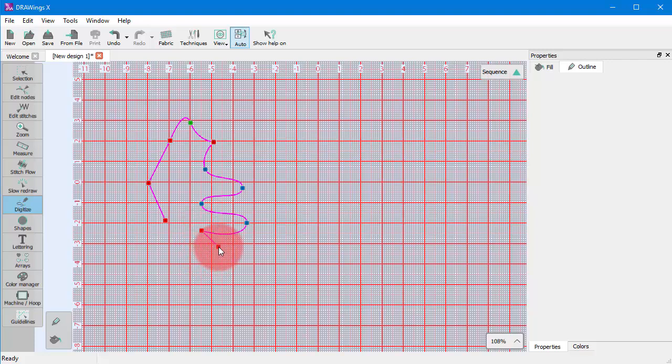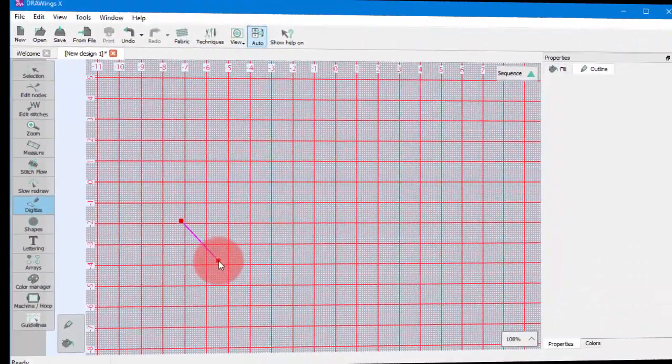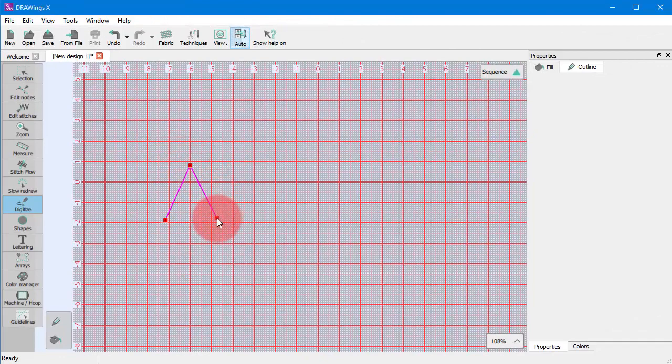While creating outline shapes, you may want some shapes to be embroidered together and others to be separate. For example, if you want this part to be embroidered together with the next one, they should be sections of the same object. Using a single right-click, the current section is finalized, while the tool remains active in case you need to start a new section.